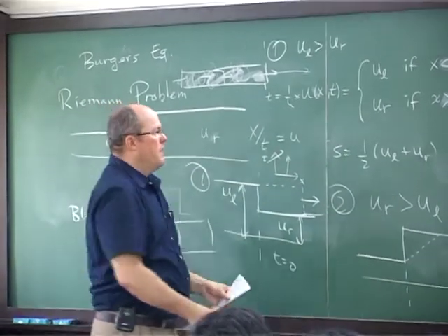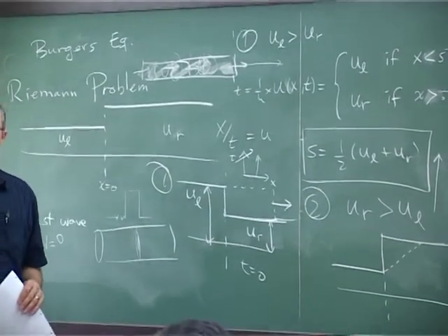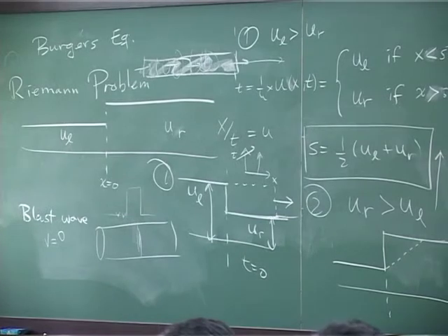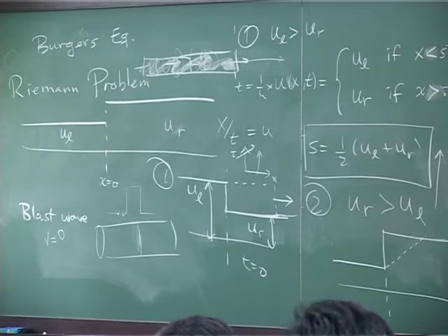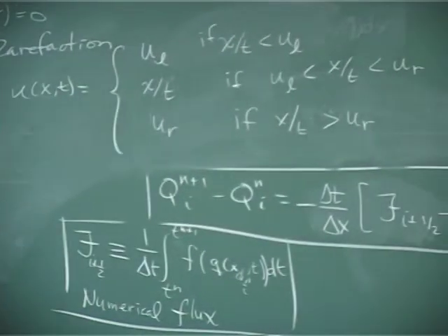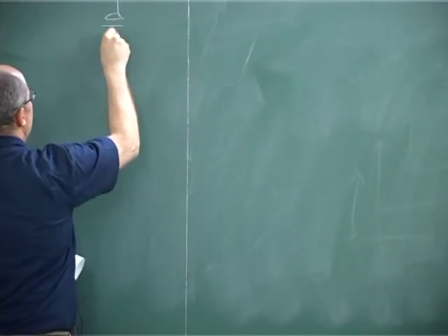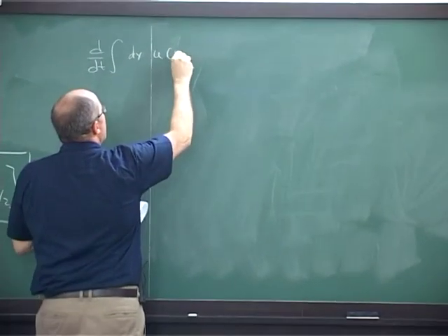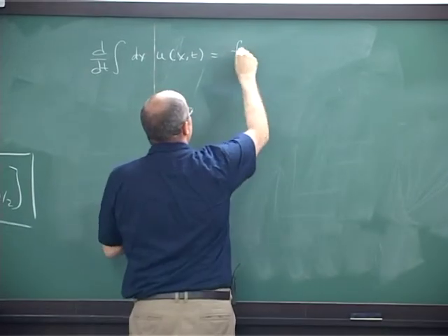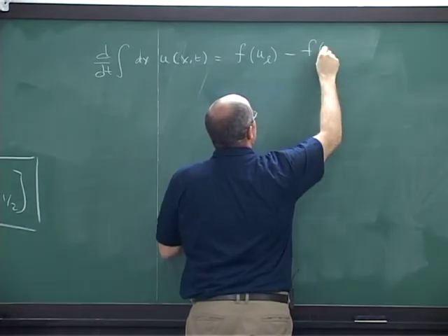and raise the screen. And in Burgers' equation, I just told you that this was the speed that the shock would travel at, the average value between the left and the right. That probably kind of makes sense, but I want to show you how that's calculated because the same type of calculation is used for the fluid equations, even though they're more complicated. If we think about our conservation law here, what we wrote down at the beginning, I'm going to simplify the notation a little bit.